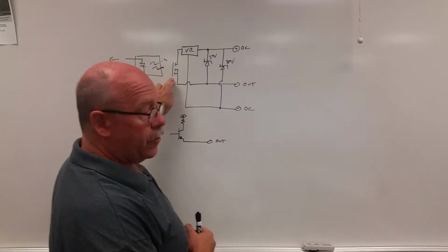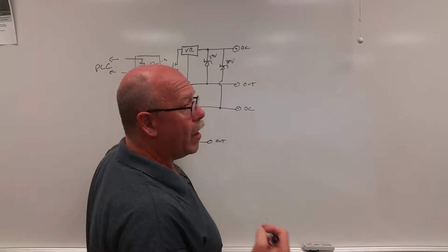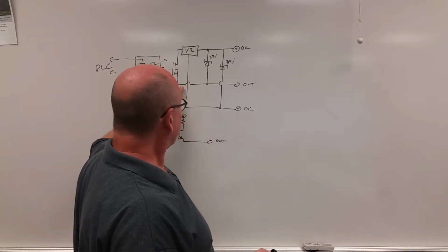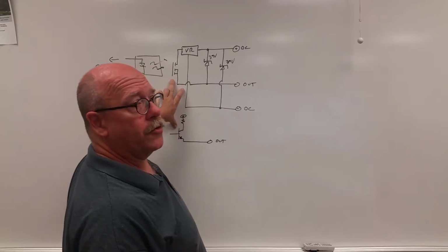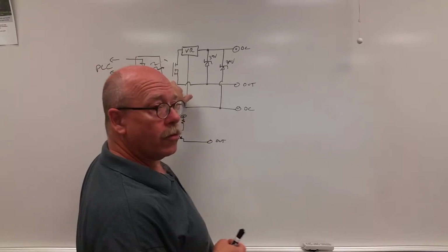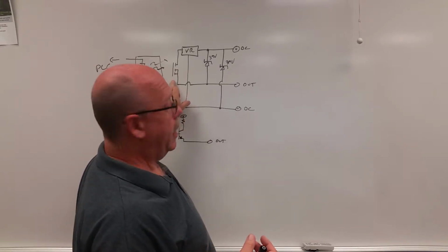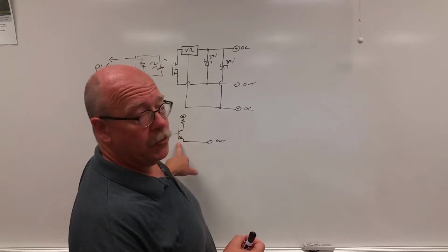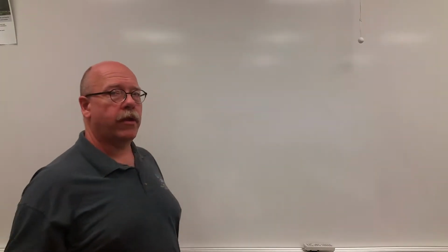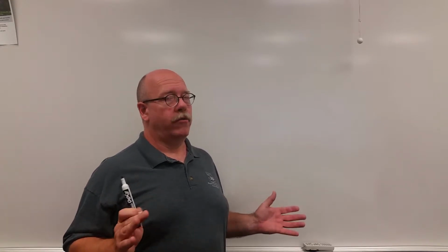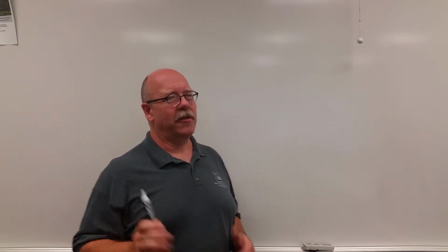Also, the FET's turn-on resistance can be quite a bit lower than a transistor. This is important for power dissipation, so it allows higher power to be sourced from the output module that has a FET versus the output module that has a transistor that would have the same size heatsink. I will now talk about sinking and sourcing outputs, a general overview, not specific to the Allen Bradley.